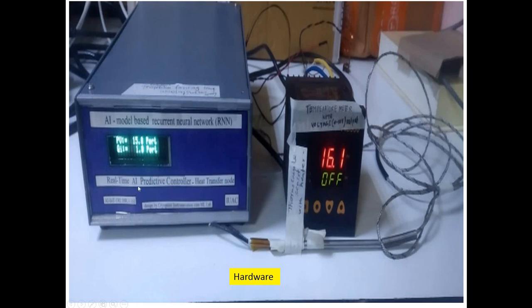However, you can see that the temperature you are reading, 16.1 degrees, is from a thermocouple sensor. This is a simple meter which displays that. It gives a 0 to 10 volt input to this controller. So this 16.1 comes here as 15.8. It's almost close. Let's assume that this is also 16. Then there will be a power which is going into the heater. This heater output, that is Q1, is in 0 to 100%. This will be 0 to 100 degrees.